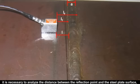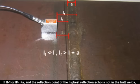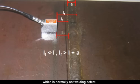If using the second echo, it is necessary to analyze the distance between the refraction point and the steel plate surface and the weld groove type, and then judge whether it is defect refraction. If LF is less than L, or LF is greater than L plus A, the refraction point of the highest refraction echo is not in the butt welds, which is normally not a welding defect.